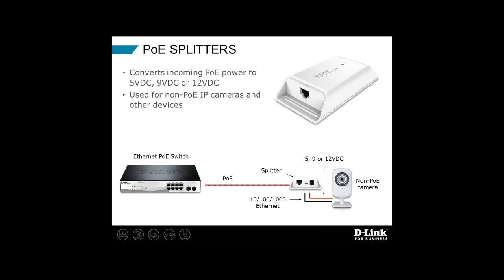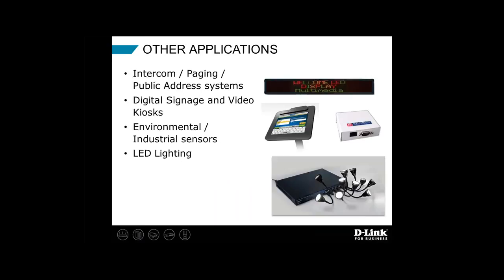of a consumer-grade camera that doesn't support power over Ethernet. But again, with a splitter, I can take advantage of PoE in my network, and I can continue to avoid the need for AC to DC wall wart type adapters that would otherwise be required.